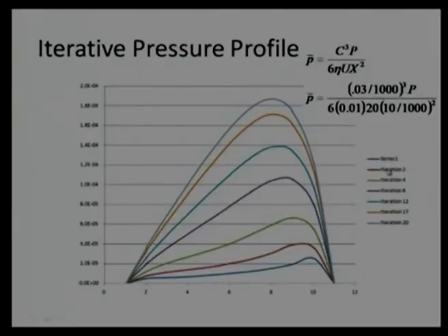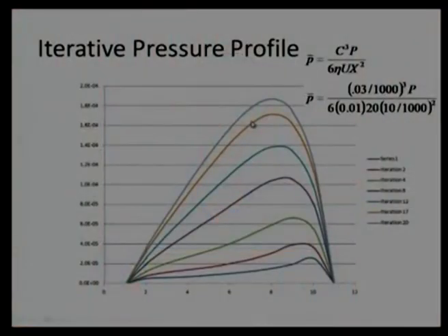So, it was a negligible effect, and that is why we consider only pressure variation in x direction. Now, whatever we have done in this case is a non-dimensional number, but finally at the design stage we require dimensional numbers. For solution purposes, to get a feeling of which term is more dominating, we have non-dimensionalized it, but coming to the final, when we substitute, we want to get the results in dimensional numbers, and that is possible using this relation.